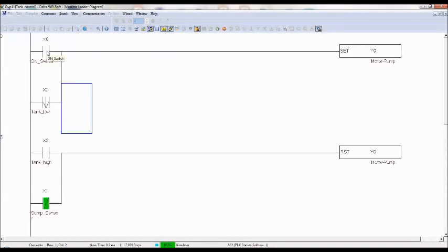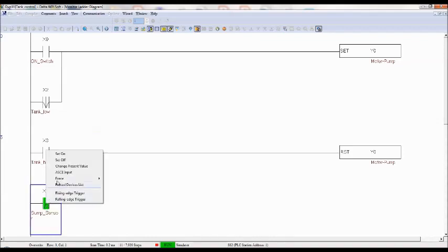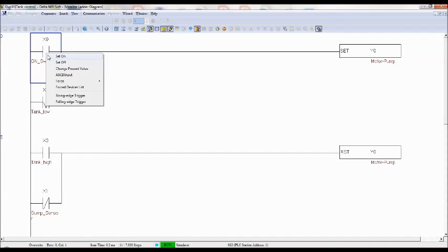See, by default there is an assumption that the sump sensor is low. First you have to make sure that there is enough water in the sump, so you have to make the sensor on. In this condition, if you press the on switch and immediately release it, there is a push button. So the motor is continuously on and pumping the water to the overhead tank.